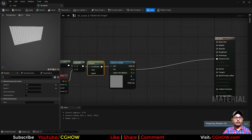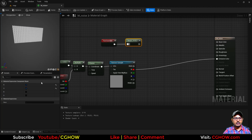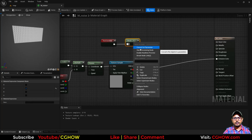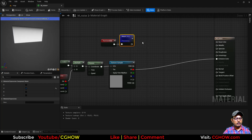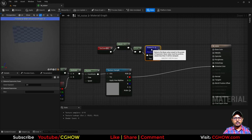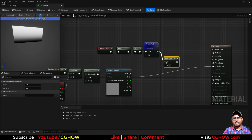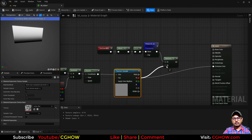Now I want this noise to only affect the top part of this mesh, not the bottom. So I'll take the texture coordinate, press Shift C for a mask, and take the green channel if I preview. Then I need to invert this so black will be down, then a power node, so I can manage how much gradient I want. Then I'll multiply these together.